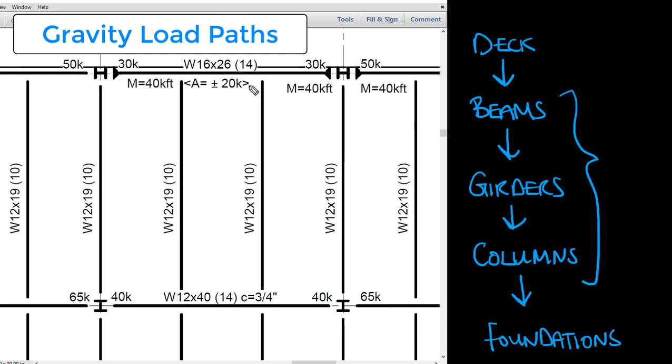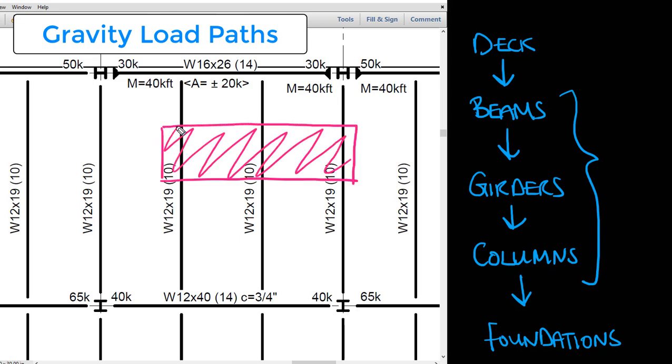Now, what happens if our load isn't uniform? What if, for example, we have a piece of mechanical equipment applying an area load like this? And suppose a portion of this area load spills over this last beam. However, the distance that it extends is not greater than the tributary width that we looked at earlier for this beam. So it may be easy to fall into the trap of thinking that none of the load will go to the next beam, and all of it will be applied to this beam, because it fell into this tributary width. However, that is not the case.